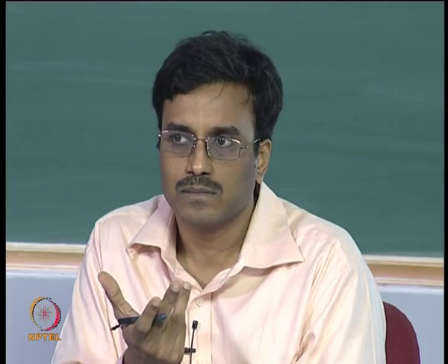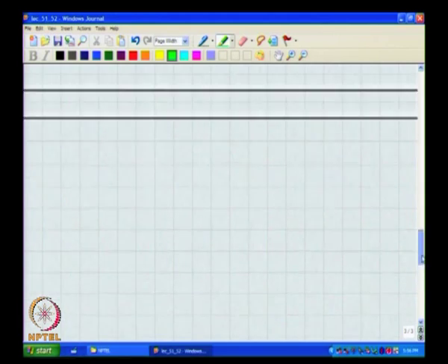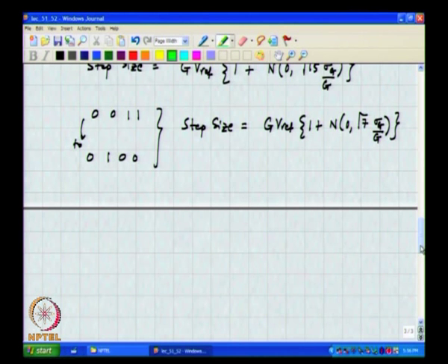Variance of the step size is nothing but what? DNL, right. So, the DNL is nothing but the actual step size minus the ideal step size, normalized to the ideal step size. So, what is the sigma DNL you get here at the major code transition?